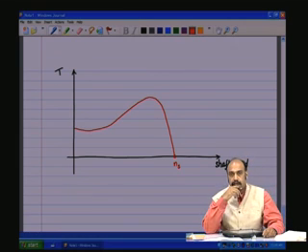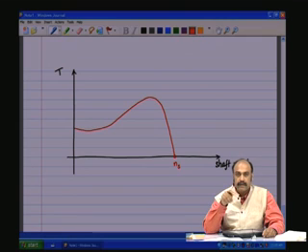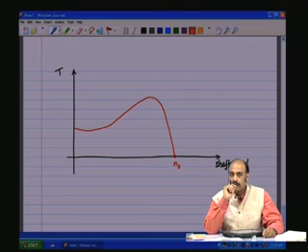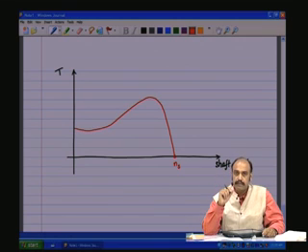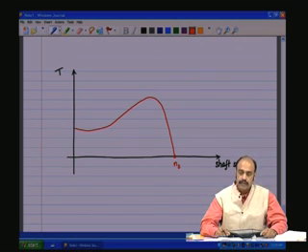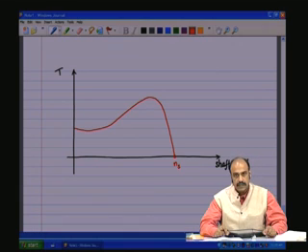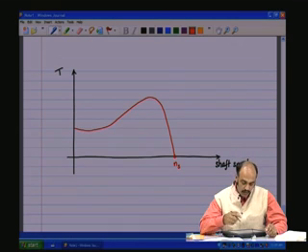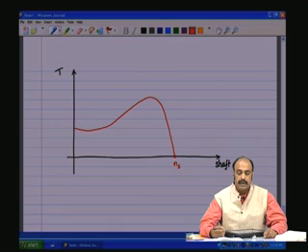Now in the wound rotor induction motor, there is a possibility of introducing external impedance, because the current can flow through the external brushes. In the external circuit after the brush, we can introduce some impedance or resistance to create some additional features in the motor. Even in the squirrel cage induction motor, the resistance of the rotor conductors plays a role on the torque speed characteristic.